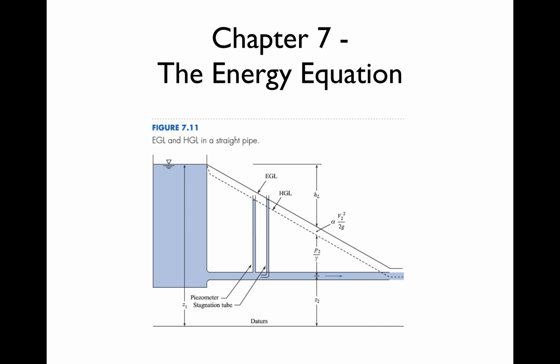But also, what you can see is that there are also head losses. Kind of in the upper part of the diagram, you can see H sub L. Let me back up here. The horizontal line at the top that the head loss is referenced to is a perfect system with no head loss.